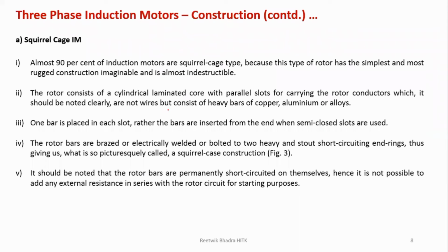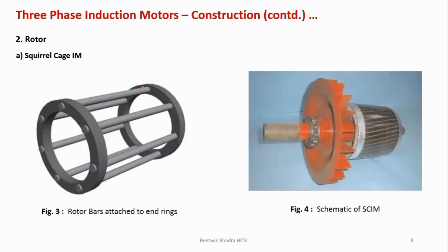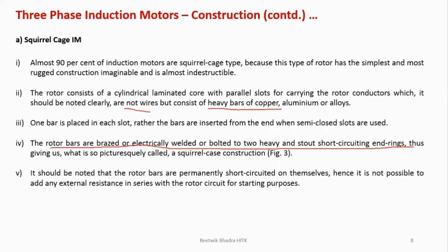And not wires. These are bars of conductor. That's why I'm telling you, these are not just simple wires. These are heavy bars of conductors made up of copper, aluminium, or any other alloys. The next very important point is that rotor bars are electrically welded or bolted into two heavy and stout short circuited end rings. So these two are end rings over here. So these are welded to the end rings to complete the entire connection.